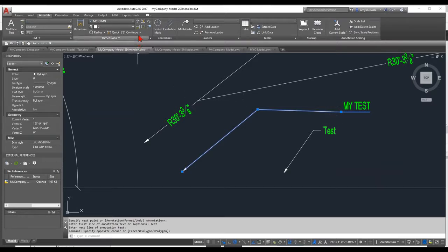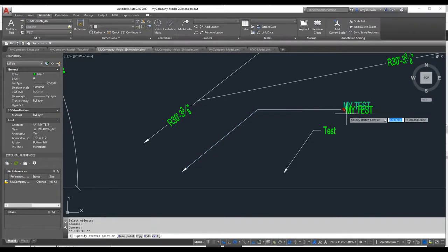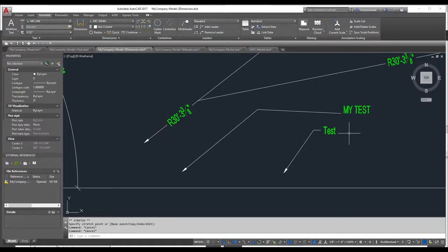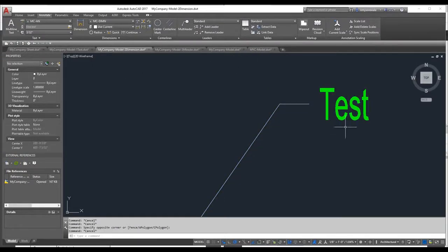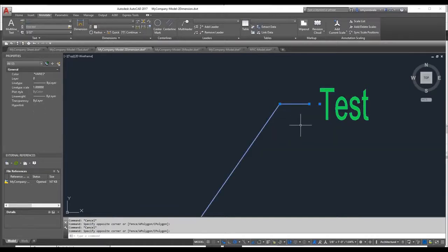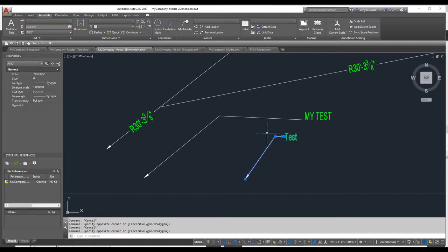If you have all those leaders, there's a quick command, by the way. It says update dimension, and it will update those dimensions for you. In this case, it was not centered, but the idea is that any new text that you create is automatically set to that centered and with an arrow, etc. So basically, the next step I'm going to get into is the M leaders.